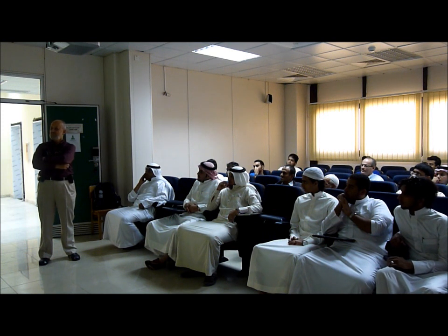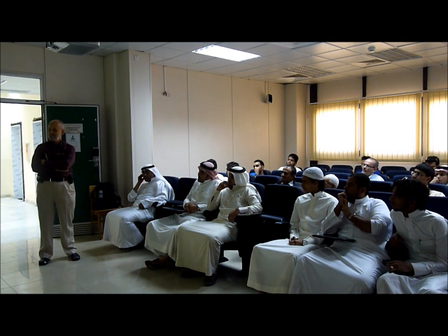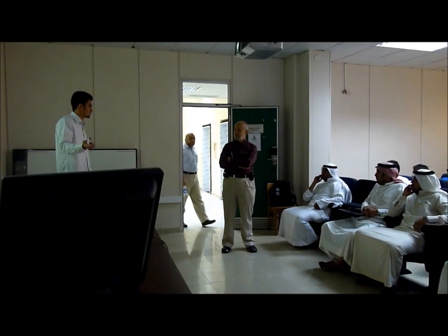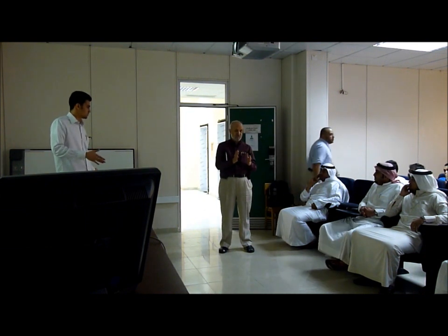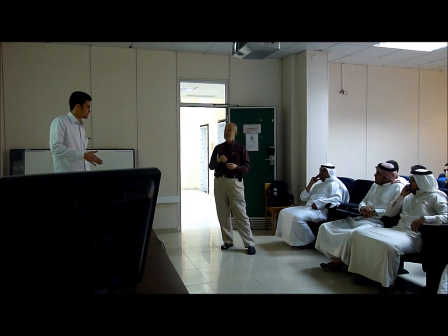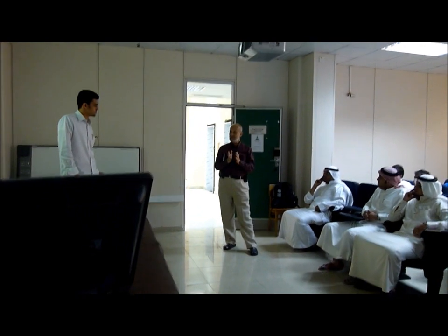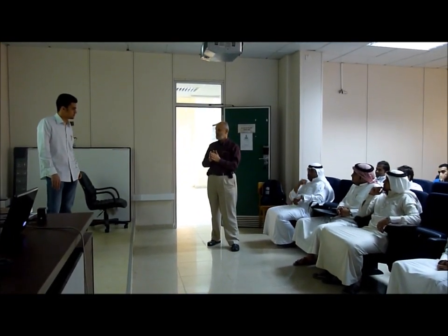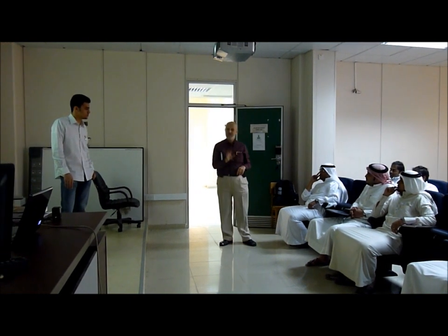This frequency is the sampling rate for the sound card, but we were using 10 kilohertz for transmitting. I see. Which is inside the listening band. When you said 44 point something, I understood because there are already available piezoelectric crystals that will be transmitted at that frequency. Those crystals are going to have narrow bandwidth. So I was just wondering how you fit your chirp signals. And because you are not using those, you are using regular ones. Yeah, I see. Okay, thank you.